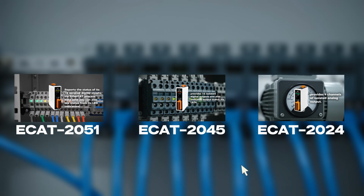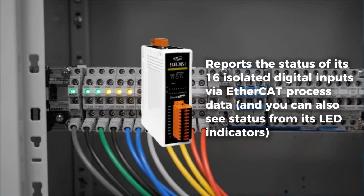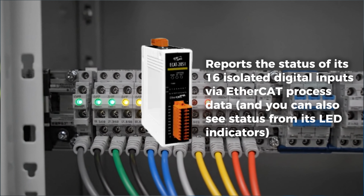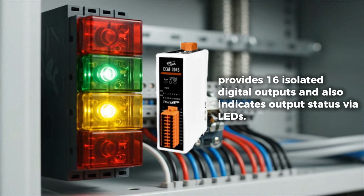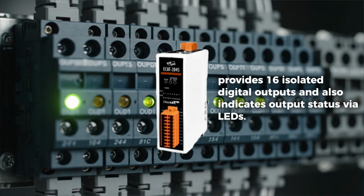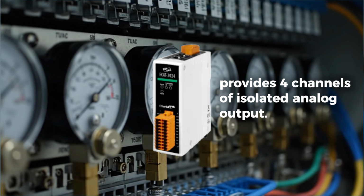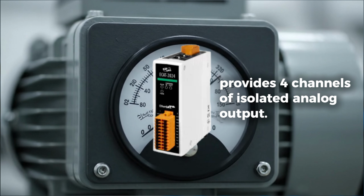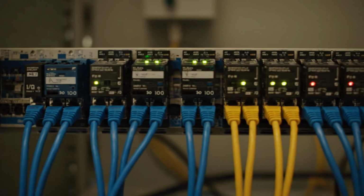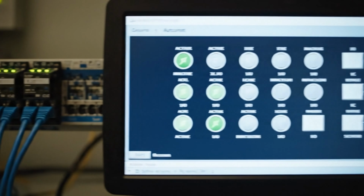For example, ECAT 2051 can report the status of its 16 isolated digital inputs via EtherCAT process data, and ECAT 2045 provides 16 isolated digital outputs and also indicates output status via LEDs. And if you need analog outputs, an ECAT 2024 provides 4 channels of isolated analog output. But the point is, EtherCAT is designed so I/O updates can happen quickly and efficiently in a single network cycle.